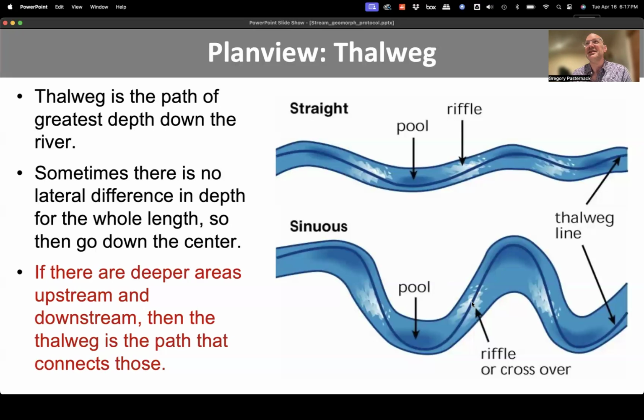That is technically the deepest part of the channel, but if it's highly localized and it's not following a clear continuous path, you'd have to really think through, can you effectively transition into that hole and then back out to continue down? Because if you do that, you sort of ruin the representation of a riffle, and you're missing that the landform is a riffle. It's like the landform is a riffle that happens to have a scour hole off on the side.